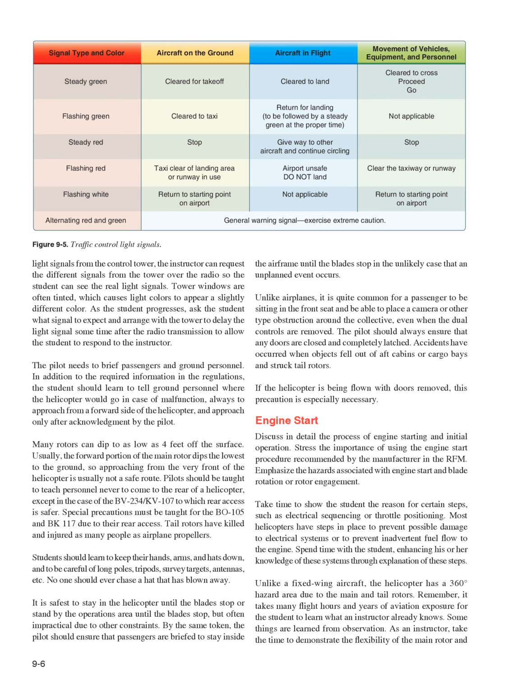The pilot should always ensure that any doors are closed and completely latched. Accidents have occurred when objects fell out of aft cabins or cargo bays and struck tail rotors. If the helicopter is being flown with doors removed, this precaution is especially necessary.